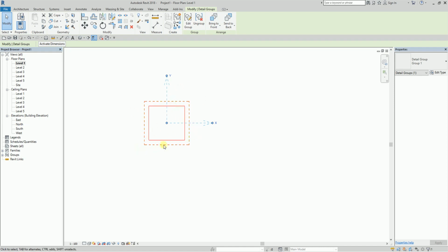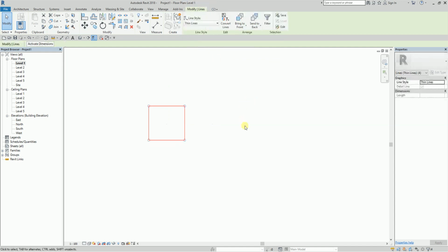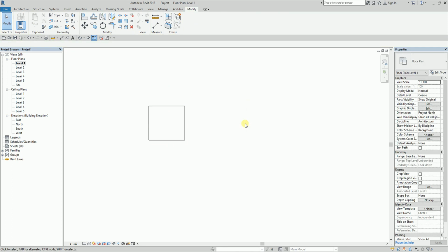So if you want to ungroup elements or set of families, you just need to select the object and then there's an option here to ungroup it. Okay. Anyway, grouping is not advisable in doing your project. So you only do this if you really need to, if the situation calls for it. But I would not advise you to use group in your project because it affects the performance of your Revit model. Sometimes it really slows, especially if you have a lot of groups.